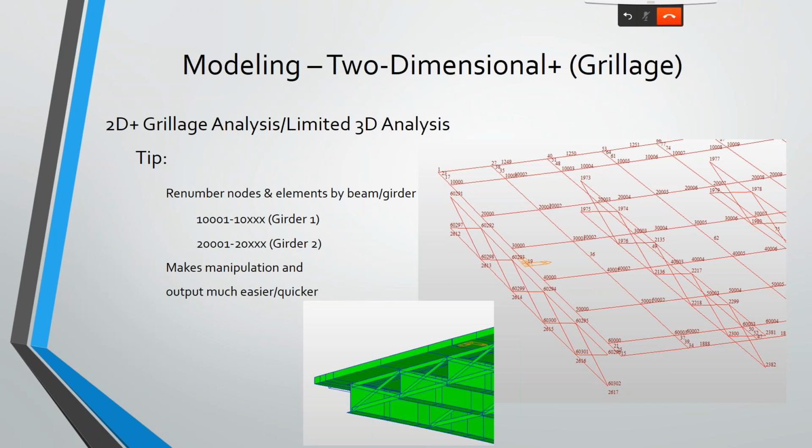Here you can see that this is basically the eccentric beam. You have this 10,000 element, 10,001, 10,002, and it's got an eccentric beam. It has the eccentric nodes that are rigid linked, and then the cross frames are fully modeled. And it also has that grid, so when you're trying to apply your live load distribution, it's creating an influence surface, and you're able to do that.